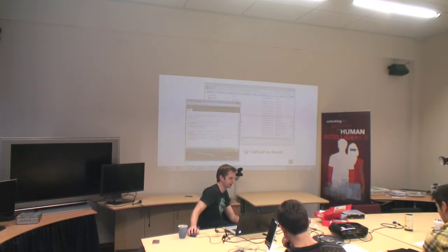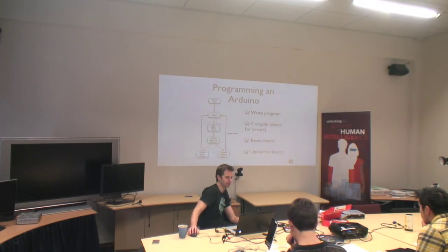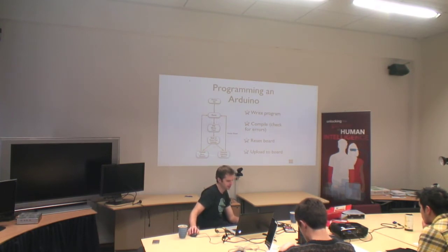So you see now the Arduino IDE tells the device to reset, and then it'll upload the code. There is still this reset and then 5-second upload thing, but when you upload a new sketch, it forces the device to reset anyway. So you don't have to worry about this so much yourself unless you're programming it without using USB. But it's neither here nor there.